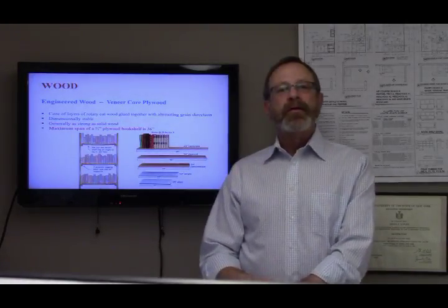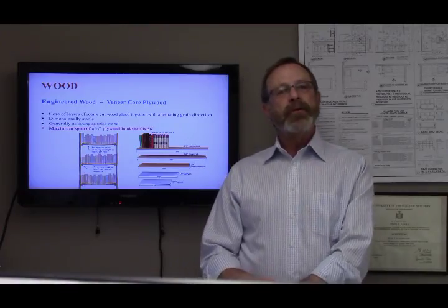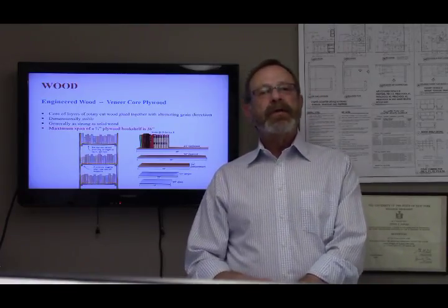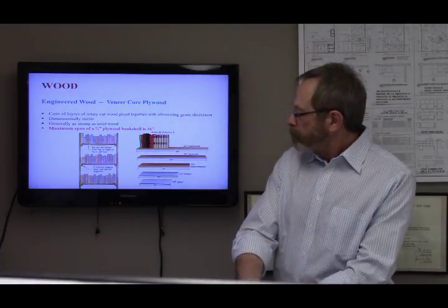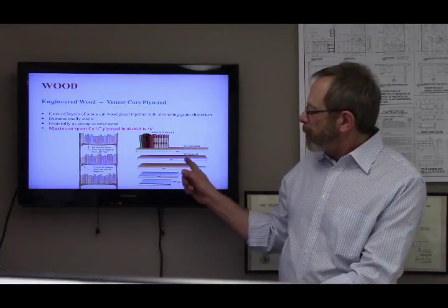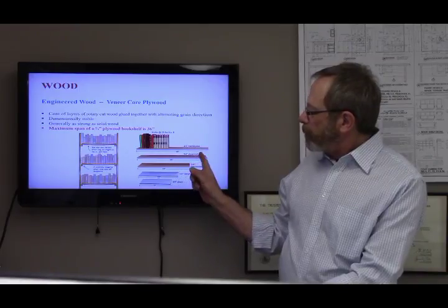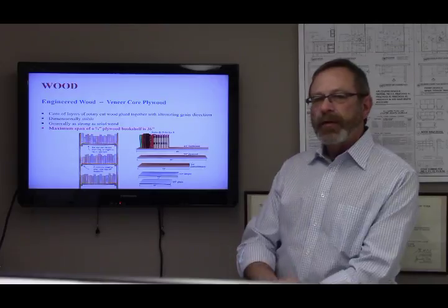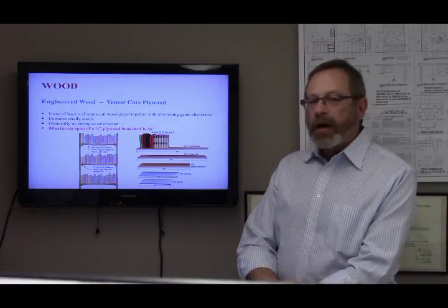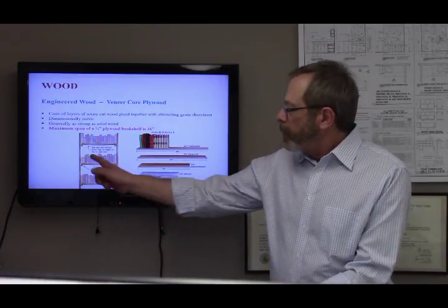Compare here the capacity of the different materials in this slide to support the identical loading of books. I'm pointing specifically out that a 3/4 inch piece of plywood will sufficiently span a 36-inch space unsupported when loaded with books.